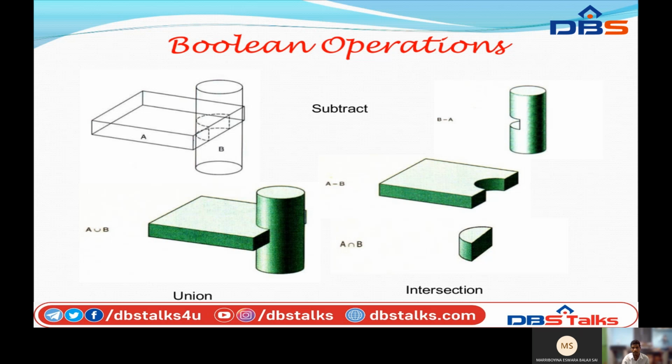Intersection means removing material in the rectangular plate similar to the cylinder, joining the two and keeping only the common volume. I'm not discussing any surfaces, only volume. These are the Boolean operations performed in constructive solid geometry.